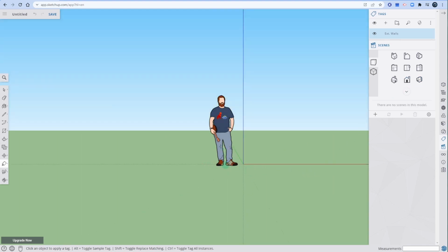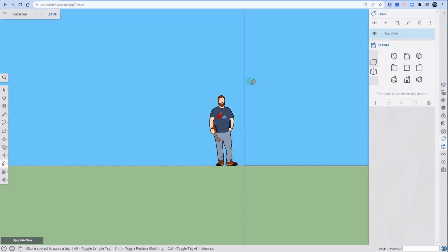You can still see all these axes. Even though I'm looking straight on, there's still a perspective view here. That's this button over here, right? This is a perspective view, while this one here is our actual parallel projections. This is the view that you should be familiar with when we drew orthographic projections. So I'm going to stay in this one for now, parallel projection. There will be times we jump back and forth just to make things easier. But I want to be in the parallel projection, top down.